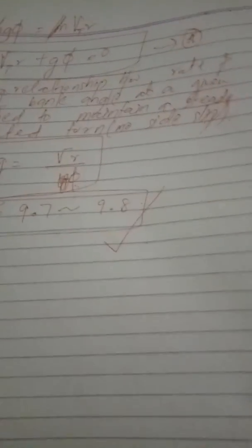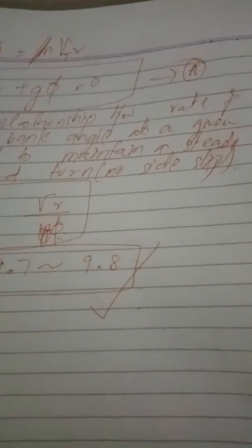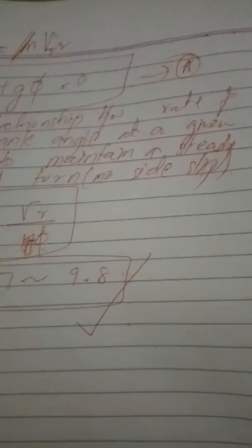If this is absolutely right, that means all the assumptions hold: if the angle is less than or equal to 10 degrees, or if theta is 0, and all the components which are very, very small are neglected or approximated to 0. Then obviously we can say that our approximation of the derivatives for the various components of the aircraft, and also because of the force and the velocity, in a steady coordinated turn are absolutely correct, and our experiment is logically and absolutely right.